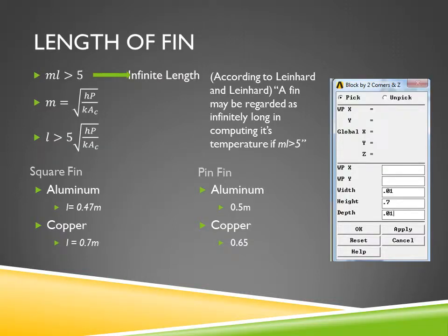Because the fin was infinite, we had to find a value to plug into our calculations and into ANSYS to find the properties. According to Lienhard and Lienhard, a fin may be regarded as infinitely long in computing its temperature if m times the length is greater than 5. So we use the equations on the upper left to find m, and then the length that would approximate an infinite pin, and the results are shown below.